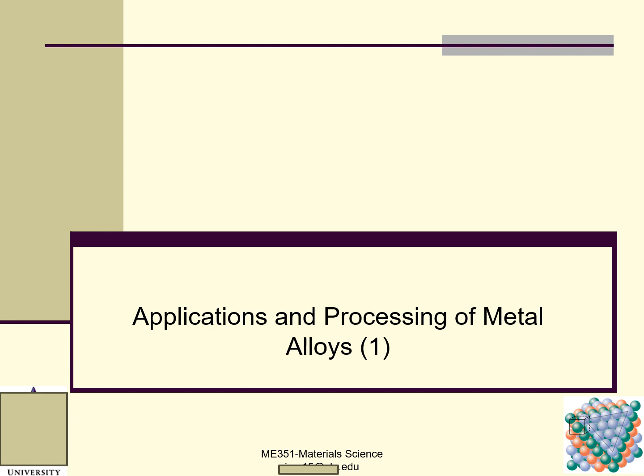One is called Rockwell hardness, one is called Brinell hardness, the third one is called Knoop, and the fourth one is called Vickers. These are four different hardness measuring approaches, and they are for different scales. For example, Vickers and Knoop hardness are for microhardness.